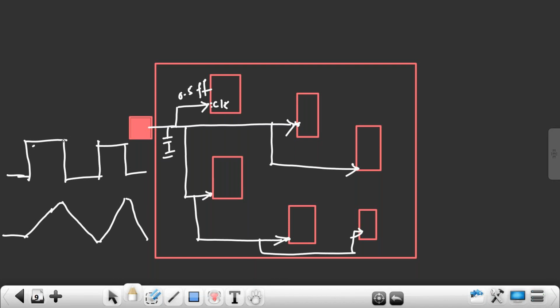Whether I have written the same clock signal? The ideal clock signal is what? Square shape, but the actual clock signal is triangular shape. The reason is that one clock port is driving many flip-flops. One clock port is driving 20,000 flip-flops. All the pin capacitance of these flip-flops becomes what? Load capacitance to this clock port. For that reason, I started losing my clock shape. For flip-flops to operate properly, I should have minimum pulse width. Minimum pulse width means minimum on time and minimum off time. That is called pulse width. Then only your flip-flop will operate properly, or else your flip-flop cannot operate properly.